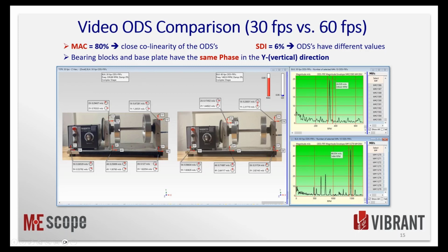The other thing now is on the animated picture, we're only going to look at 5 points: a point on the top of each bearing block, and then a point down here. You can kind of see the 3 locations where we've glued down some metal washers, iron washers, to the aluminum surface so we can use a magnet with an accelerometer. And as I mentioned, this is all in preparation for a comparison between accelerometers and videos.